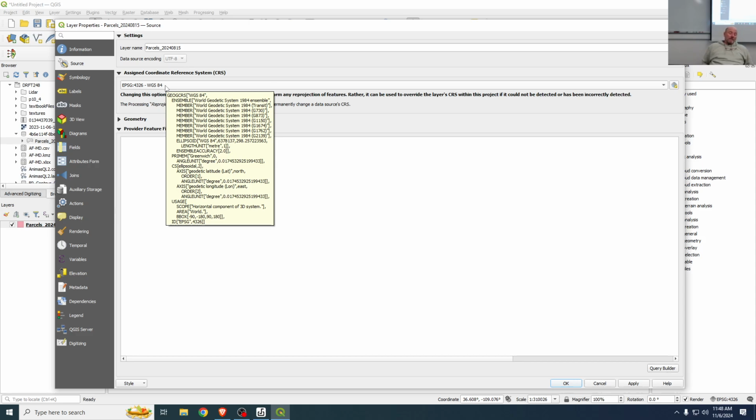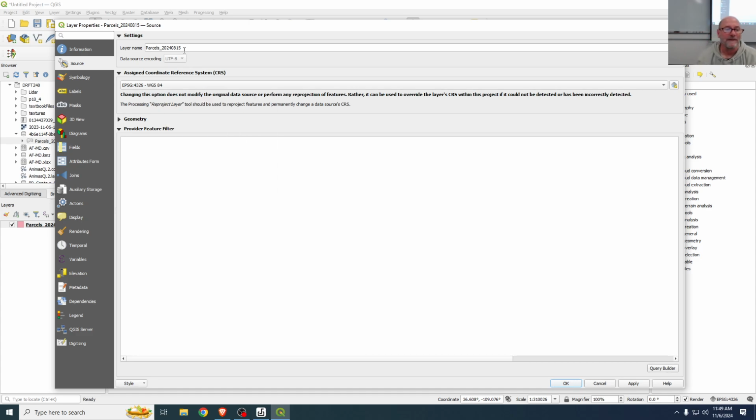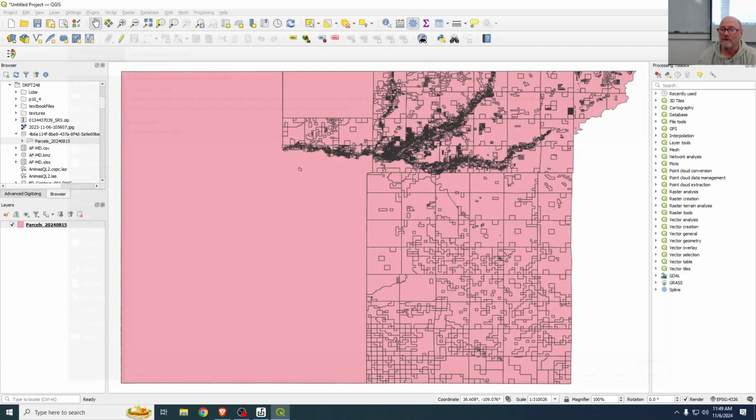So the first thing I would want to do is reproject this, like create another layer in the New Mexico West planar coordinate system, a projection that uses linear measures like feet or meters, right? So there's a tool to do this, and I think that should work pretty easily.